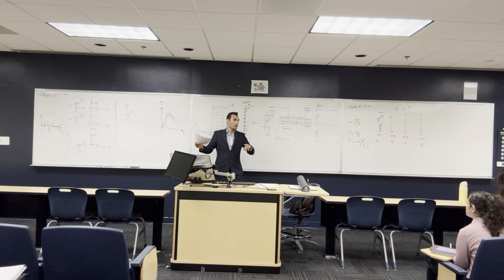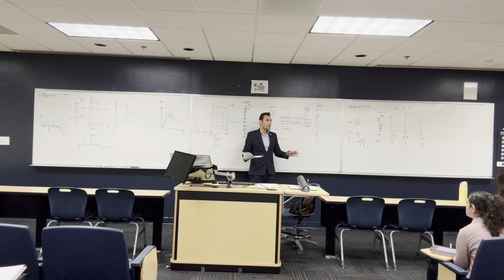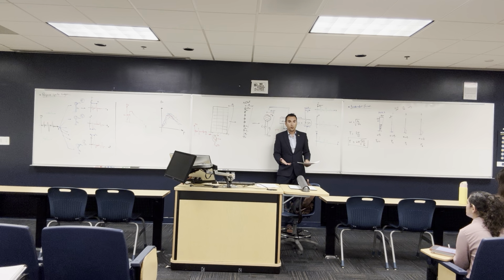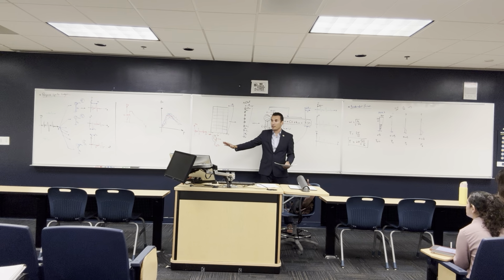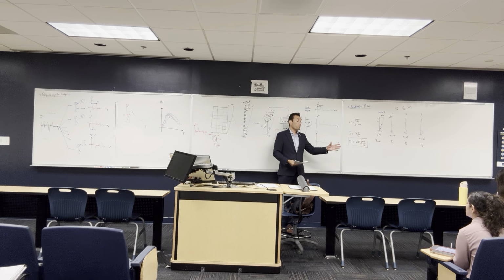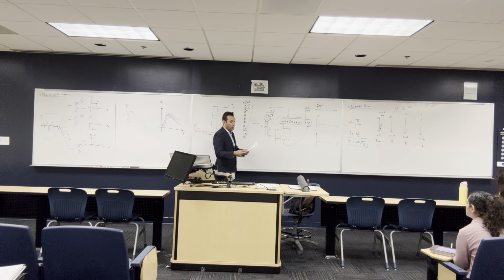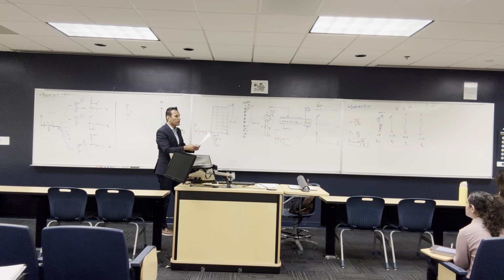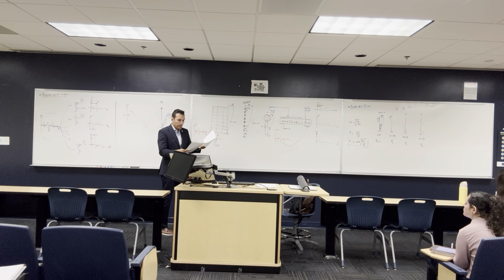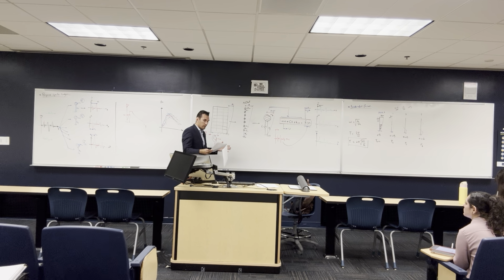But if you have a hospital, you multiply by 1.5. Let's say that you calculate the earthquake force to be 500 tons. If it's a residential building, you're going to use it the way it is. But if it's a hospital, you're going to make it bigger, 1.5 times. If it's a nuclear facility, much higher. That's what we call risk category. Then the code does some operations so that we can draw this response spectrum curve based on all these. I teach all this in advanced structural analysis, but I'm not going to teach it here.